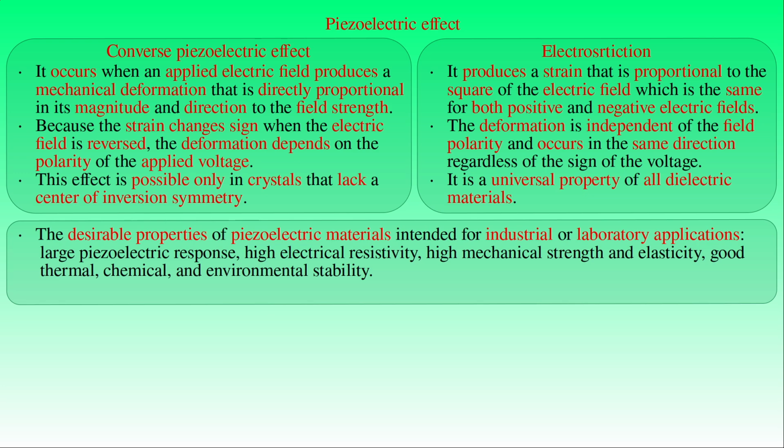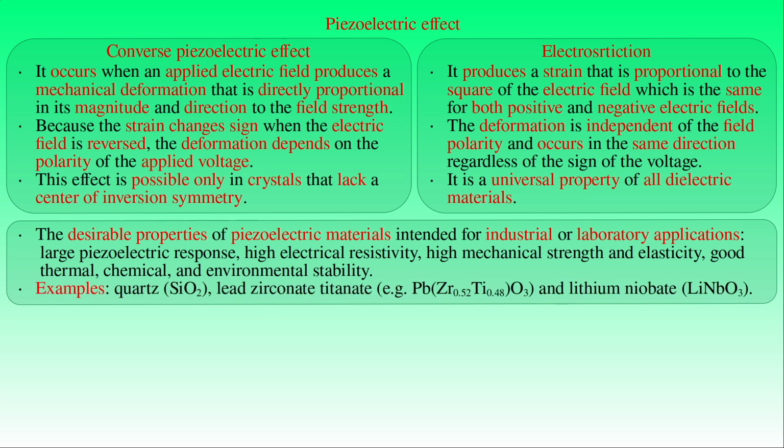Finally, they should possess high mechanical strength and elasticity, as well as good thermal, chemical, and environmental stability to ensure reliable long-term performance. Examples of such materials are quartz, which is widely used for frequency standards and precision sensors, lead zirconate titanate, which is the most widely used industrial piezoelectric material, and lithium niobate, which is valued in high-frequency acoustic and the manufacturing of optical devices.